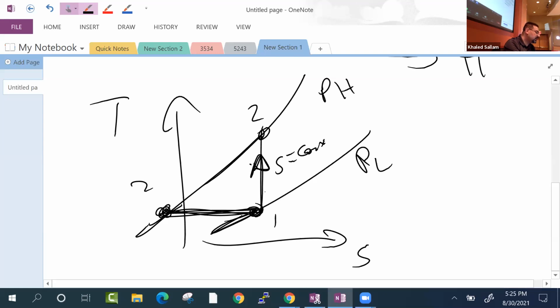So what they do is they go up one stage, just take the pressure this much, and then cool again to T ambient. Then go up a little bit, then cool again to T ambient, and then go up. So this is not really isothermal, but this is only 3 stages. Well, maybe you can make 5 stages. Maybe you can do 8 stages.